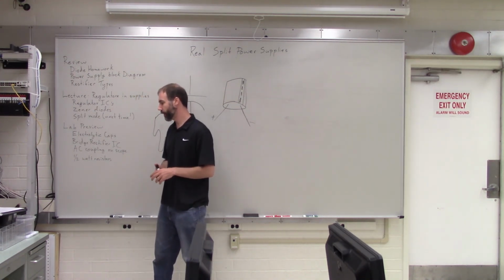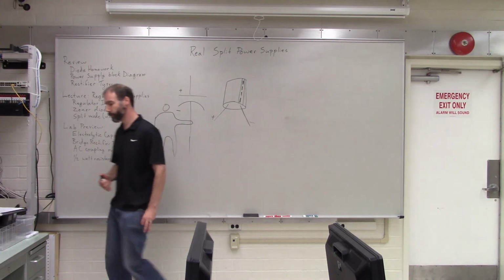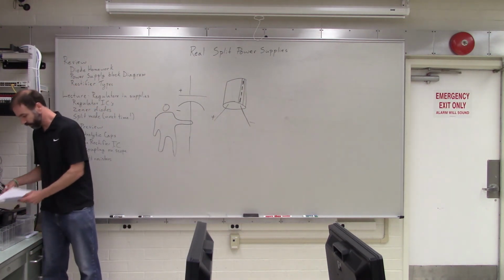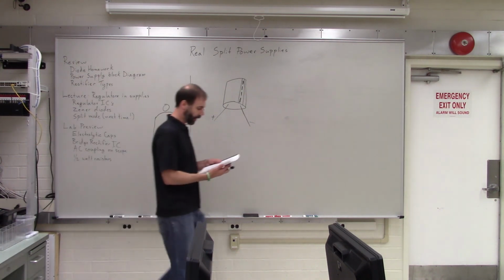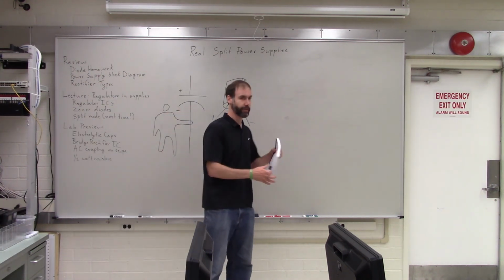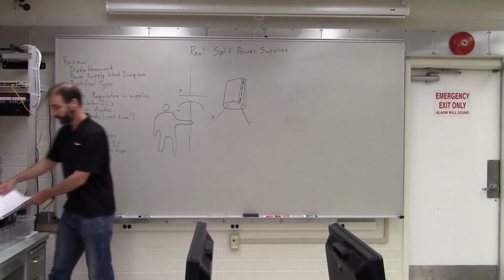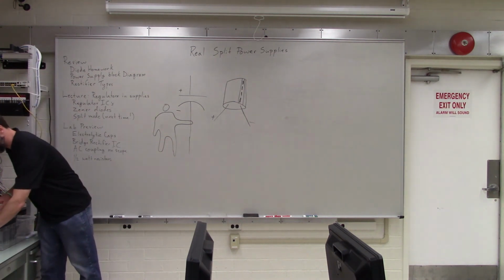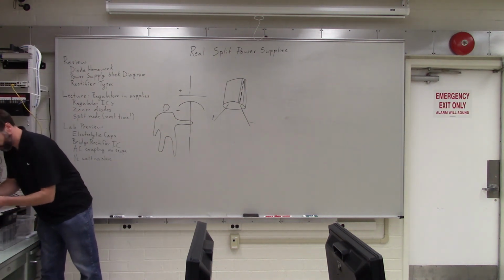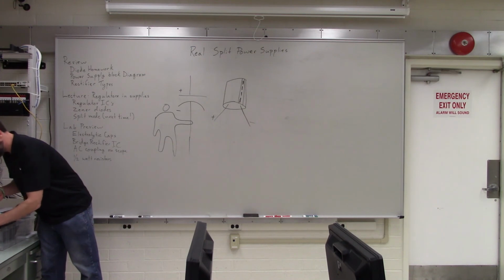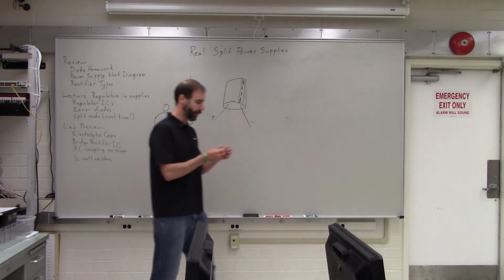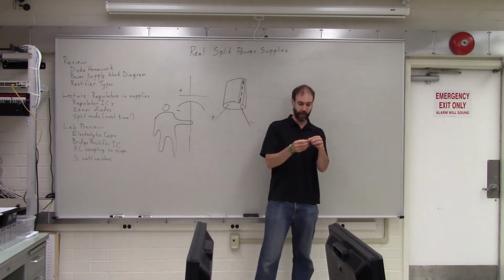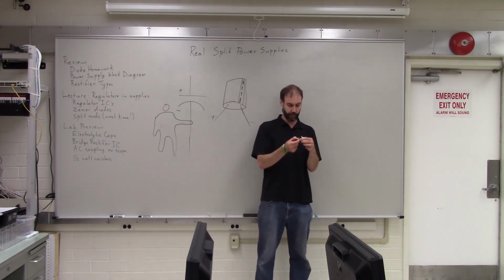I do want to point out that we have half-watt resistors for this lab. So this calls for two 1 kilo ohm half-watt resistors. The half-watt resistors have the same color codes as the normal resistors, but they are about twice as big around.